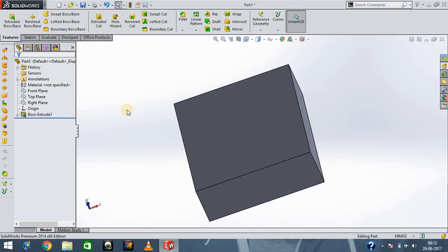See how reference planes are created. It is called reference because it is created in reference to another pre-existing plane or edge or points. There are many ways to create a reference plane. Like you can offset a distance, you can create at an angle to a pre-existing plane. You can use lines, points, perpendicular, parallel. There are many ways. We'll see each of them.